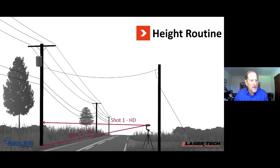The second shot is to the base of the pole. Now this is just an inclination shot, just a tilt shot. You don't need any kind of return for the distance. So if the base is obscured, you just visually estimate where that is and pull the trigger. Now you just take your top angle. In this example, we're going all the way up to the cross arm. This will complete the solution, and a height value will be calculated.